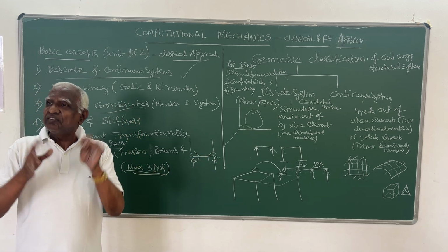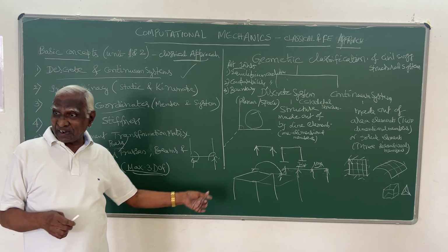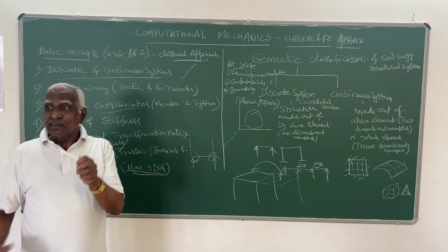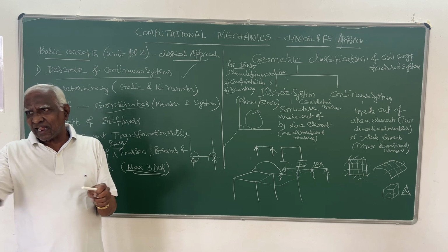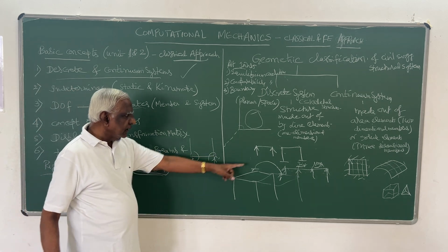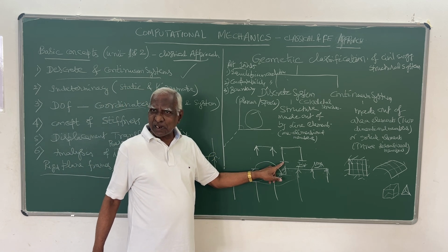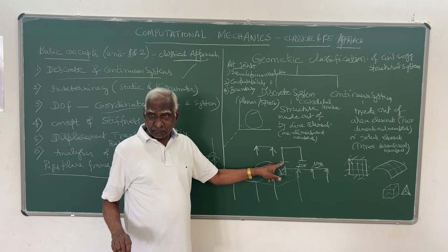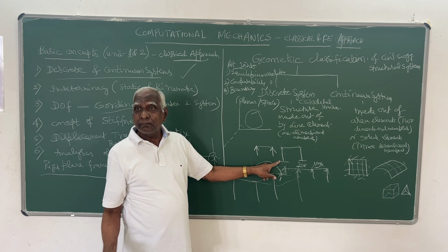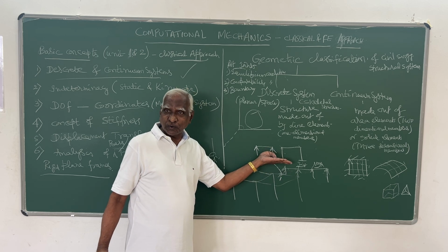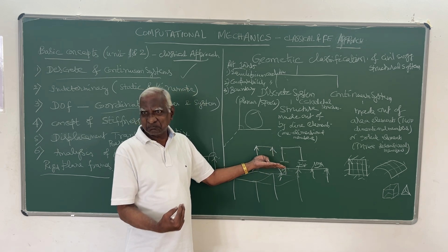It is there. If it is restrained, it is boundary. Usually at the boundaries, it is restrained. To restrain that, there has to be a reaction. That reaction has to be determined. So at boundaries, this displacement is not there. Force will be there. There must be force to oppose that. So that force is supplied by the support. That we call the reaction.